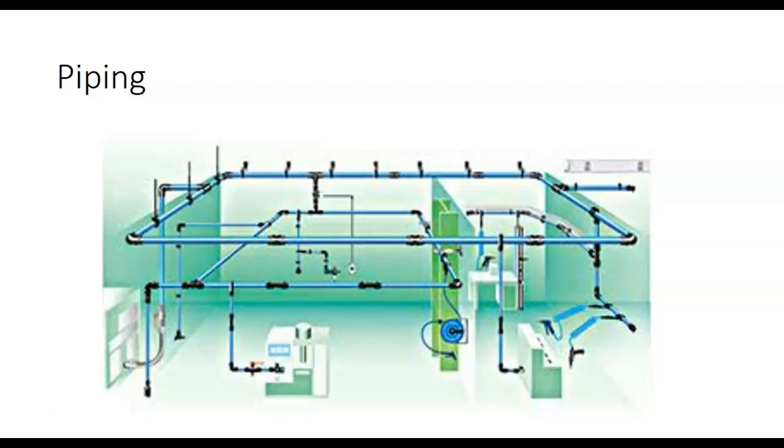Dual stage means you have a big piston, and then it compresses it and puts it into a second piston. If you put it back in the same size piston, it would uncompress. So you can tell multi-stage compressors because the output piston will be smaller, and it's got a big old cooler on it. If y'all haven't been in there, it's got a radiator on it to cool it down. And then it purges every once in a while. I don't know if y'all hear it hissing in there. That automatically happens, it's on a timer. What that does is it's supposed to get the moisture out, but undoubtedly we've got a little bit of a problem.